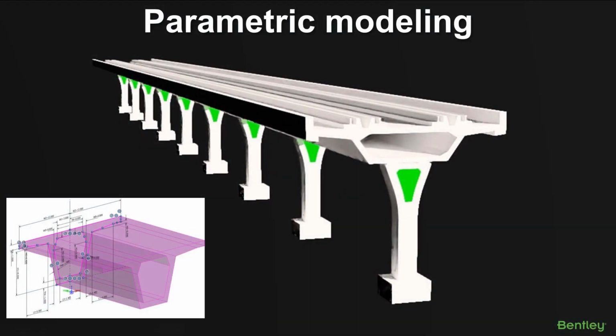We mentioned MicroStation's parametric modeling capabilities. In a nutshell, parametric modeling allows you to draw your models, set some rules for driving these models using dimensions and/or variables. You draw your model once, and then you can quickly change its size by only changing a set of parameters that you defined. This makes reusing and recycling your content much easier, while at the same time, it helps you to reduce the size and complexity of your content libraries.